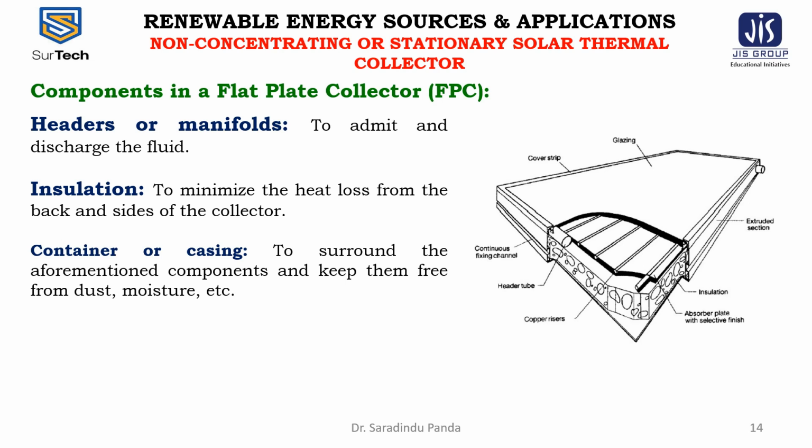The heat transfer fluid, maybe water or the antifreeze mix, is pumped from the hot water storage tank or the heat exchanger into the collector's bottom header, and it travels up the risers, collecting the heat from the absorber fins and then exits the collector out of the top header.